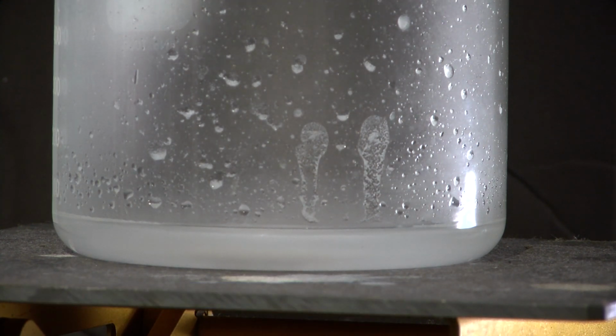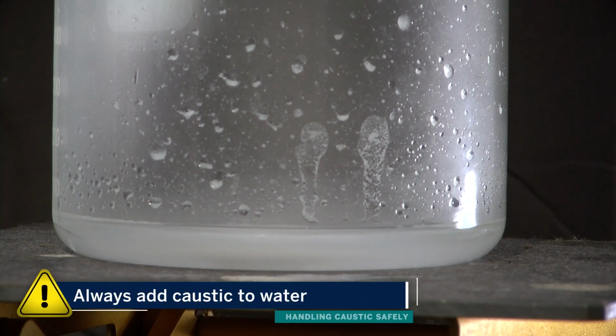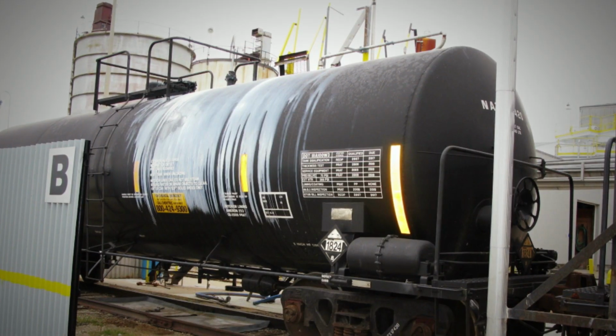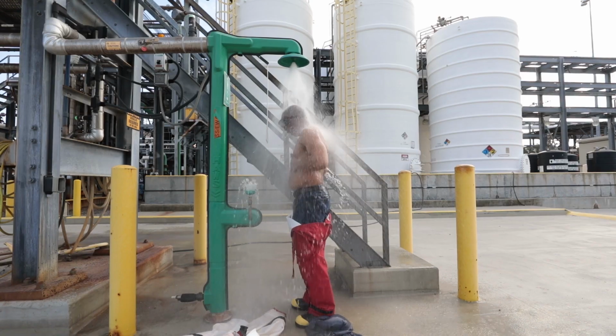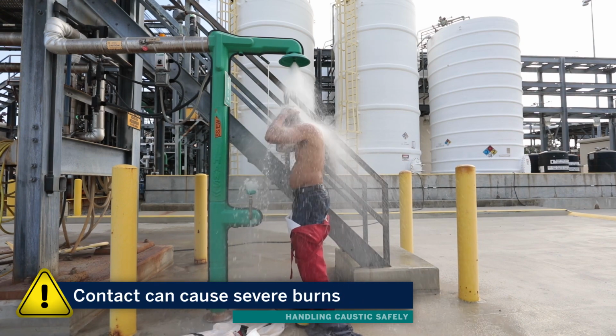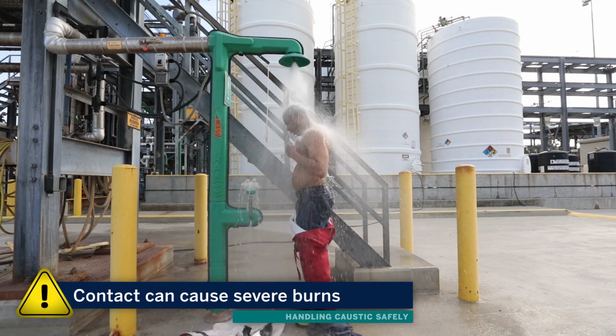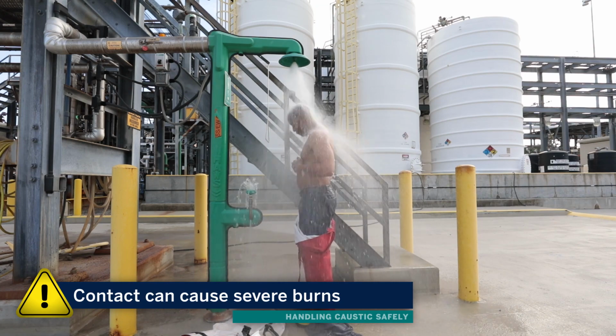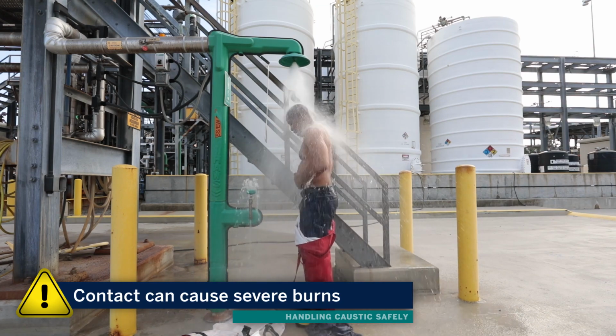Water reacts with caustic soda. The reaction will be exothermic, where heat will be released. So for safety purposes, always add caustic to water. Caustic solutions are highly corrosive and need to be handled carefully. Contact with eyes or skin can cause severe burns. You may not initially feel caustic when your skin is exposed, so be sure to wash any potentially affected areas.